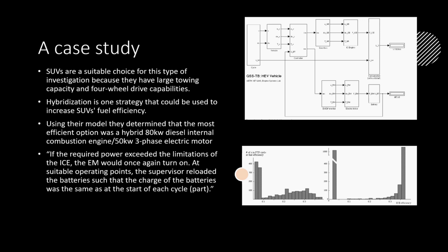The design was so that it would be able to maintain that towing capacity on a 6% grade indefinitely and still have the regular acceleration characteristics of a conventional SUV. Because of the smaller engine size, the top speed is lower than a conventional SUV, but that is not very relevant to most users who will not be driving at a top speed, even on highways. And the vehicle's mass was increased by 100 kilograms.